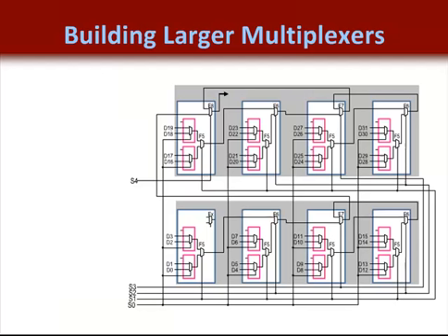This slide shows how the F6, F7, and F8 MUXes can be combined to create 8-to-1, 16-to-1, and 32-to-1 MUXes respectively. Because the F5, F6, F7, and F8 MUXes can be inferred automatically by all the high-end synthesis tools, most designers do not instantiate these resources. However, a case statement will be required. You should also note the specific sizes of the MUXes that can be made with each of the dedicated MUXes.